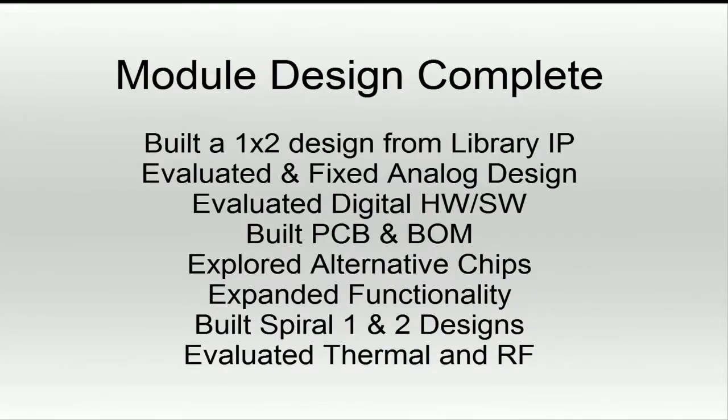So in this time, you've seen me build a design from IP. I've evaluated and fixed an analog problem. I've evaluated my digital hardware, and built a platform to develop my software. Built PCB, bill of materials, explored alternative chips, expanded functionality, and built both Spiral 1 and 2 designs, and started to address some of the physical properties of the system. So this is all in the Metamorphosys tool, and all in a very, very short amount of time. Probably half an hour or so I've gone through a lot of these different analyses.